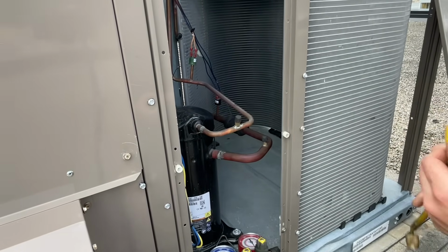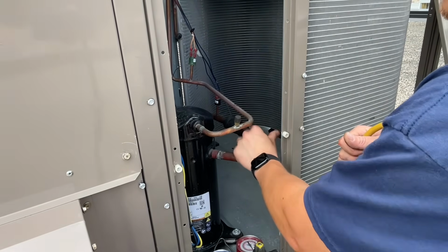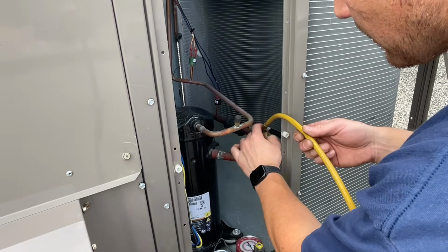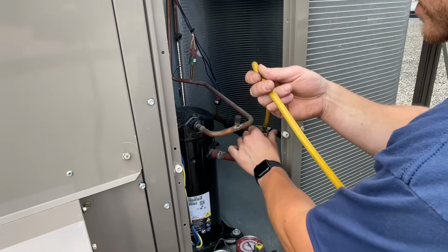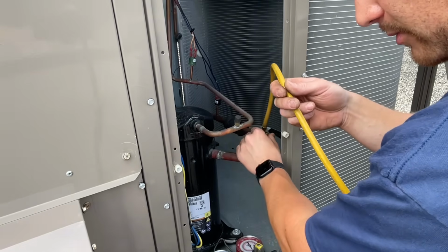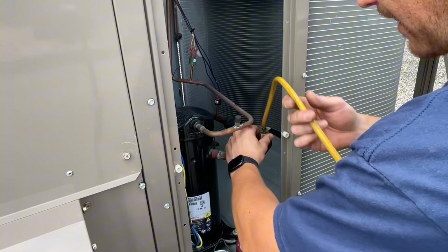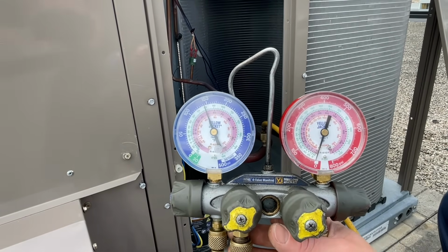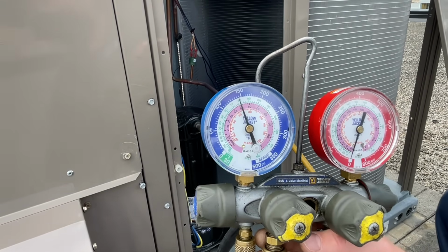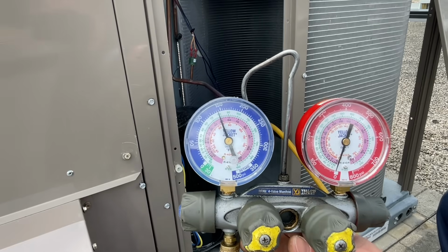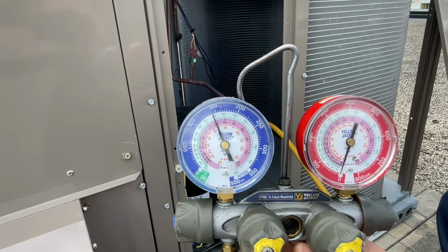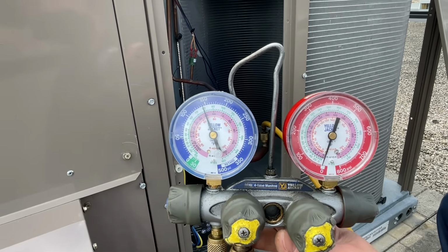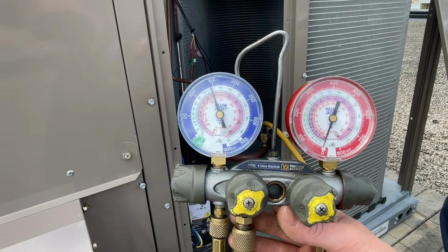Let's check our running pressures. By the way, if you're wondering why my low side is now yellow, I had to switch my hoses because of the failure I just showed you. Does it matter what color your hose is? Absolutely not, but we're loaded. Fully loaded up. This is 410, guys. We're using the pink scale. We're running almost at a 50-degree evaporator coil. This unit is working to full capacity, and it's doing all it can.